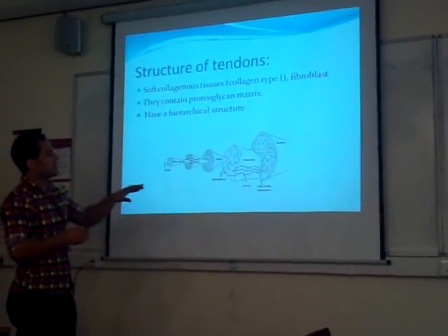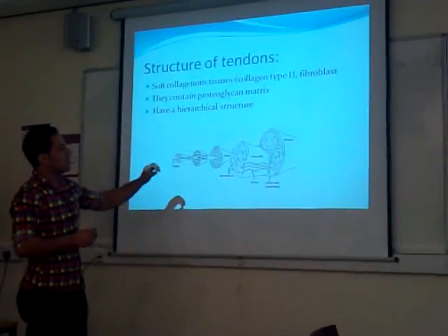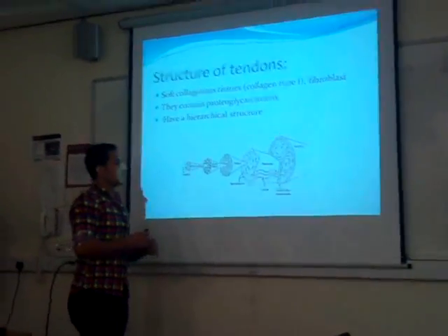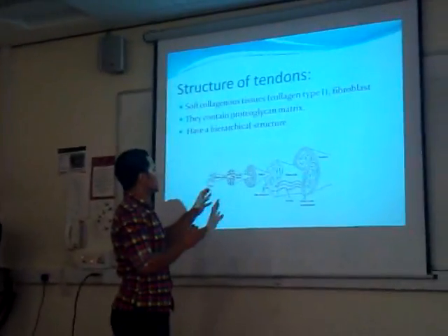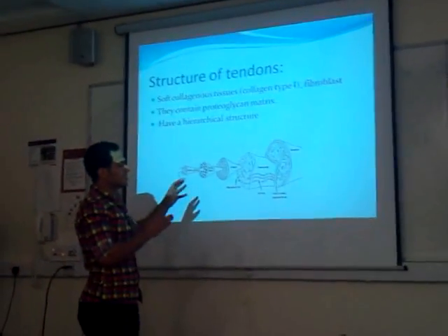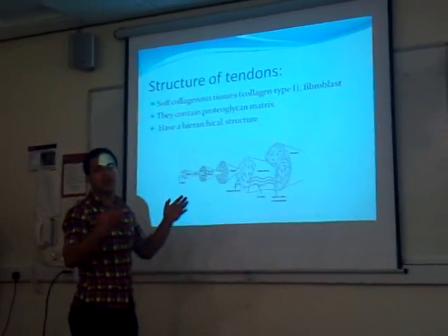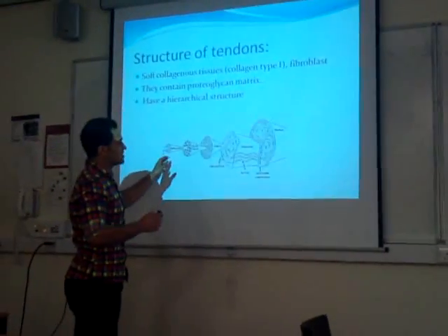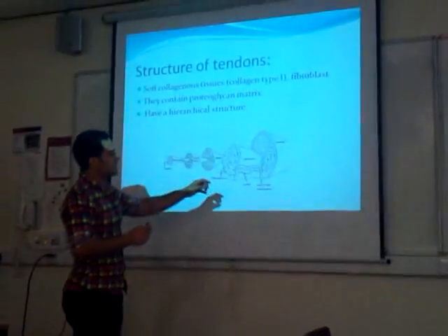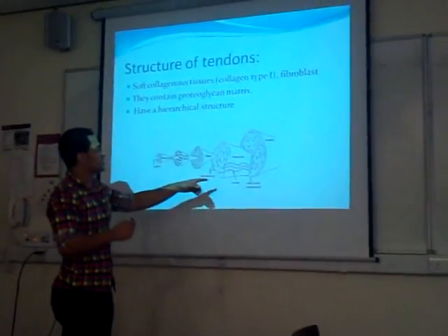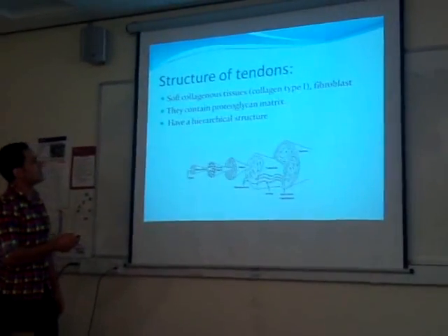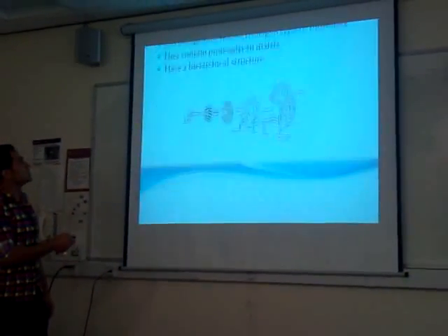So you'll find the crimps basically in areas that are subjected to more stresses, because when the crimps are subjected to tensile stresses, they act as a spring, so they uncrimp. And when they are subjected to compressive stresses, it increases the compressive strength and stiffness.